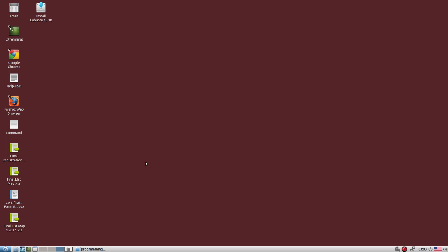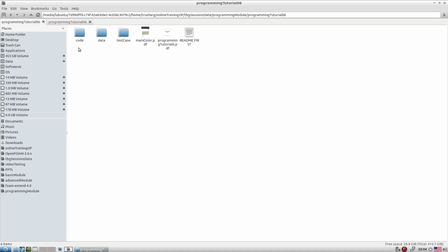So let's try to understand a few concepts of how one can develop the new turbulence model. In the previous case we adapted the template, so we ultimately constructed the template, and now we know how to fetch the template out of the actual source code. So let's do the same task again. For that, let's go to our code area, and we try to fetch the template from the extended